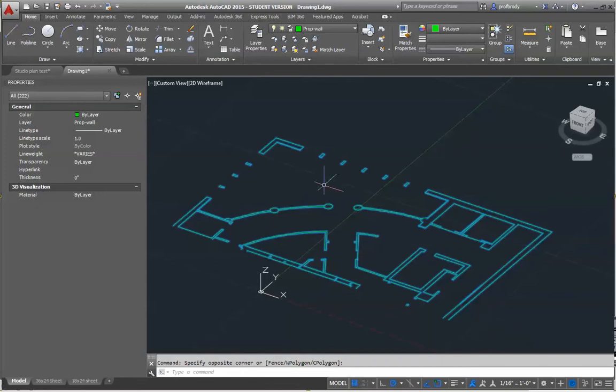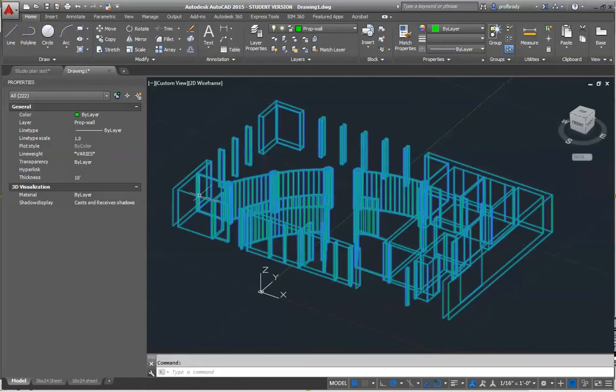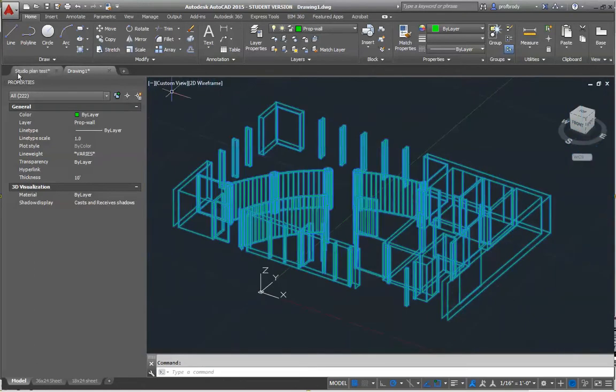Anyway, I can just select all the walls, and like I did in class, give them a thickness. If I remember correctly, you all said 9 feet was the height of the ceiling. So I'll type in 9 feet. Now, of course, this project, maybe I'll give myself another foot of ceiling because it's a big project. Okay? When you hit Enter, like magic, you have a 3D model.